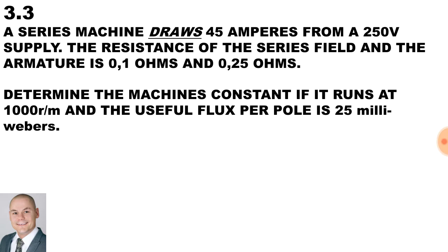Therefore, current remains the same and voltage is divided. The word draw is used, which also indicates that this is a motor, as a motor draws current from the supply. Now, first of all, in order to work out the constant, we'll first have to calculate the generated EMF.